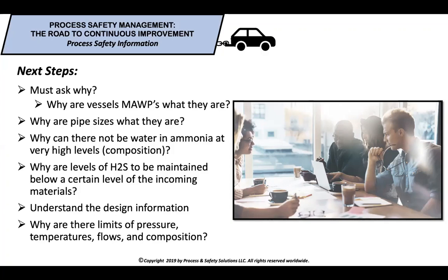Same goes with piping. Oftentimes, engineers will size piping to address a specific process safety issue. For example, not too long ago, we did an investigation on a fire that was a result of piping failure. As we began the investigation, we noticed that the inlet piping at one point in time was 12-inch, and then within about 2 or 3 years, it was replaced with 8-inch.